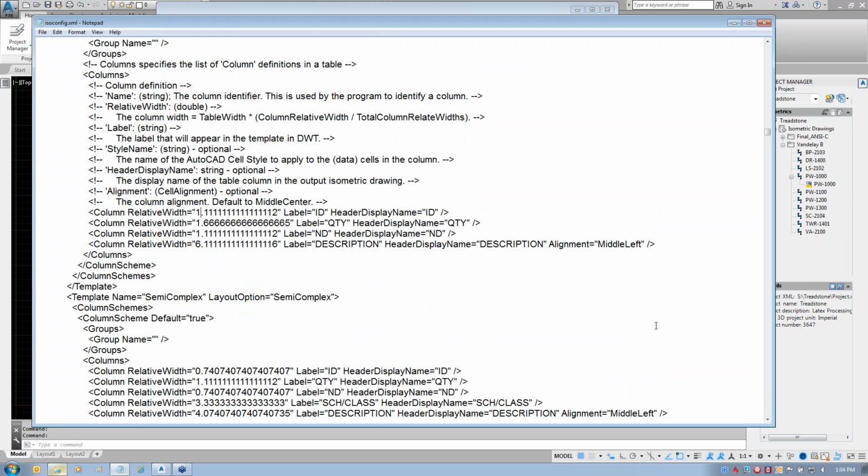And so right here, since I know I have 5 inches in thickness, as long as these total up to that 5 inches, it will give me exact column width. So I'm going to make this one 3/8 of an inch. We'll make this one 1/2 inch.